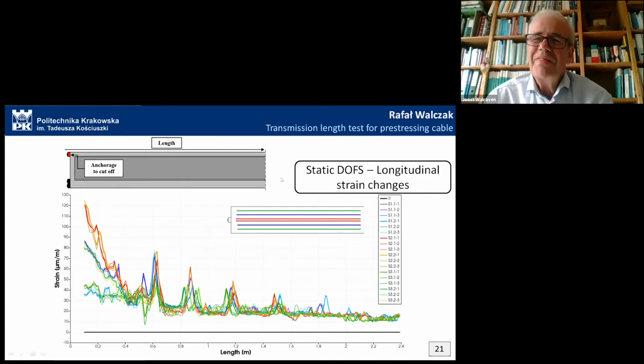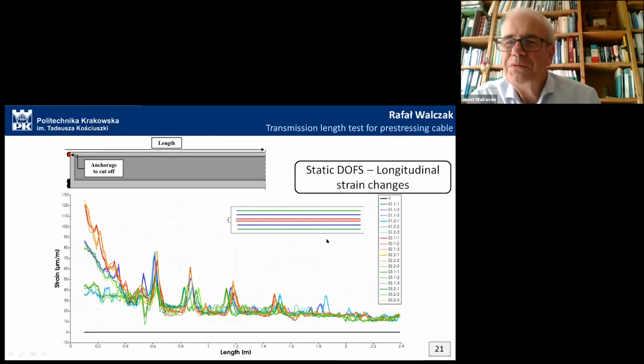Okay, that's very interesting. If we widen the picture a little bit, then of course the question is, how can we make a risk analysis of bridges? What would it mean, for instance, when the anchorage breaks and we have to rely on the slip? And you said you also look at the shear capacity. What would it mean if this happens? Is the bridge then really near to collapse, or can it really collapse, or is there still a margin? Can you say something in general about this?